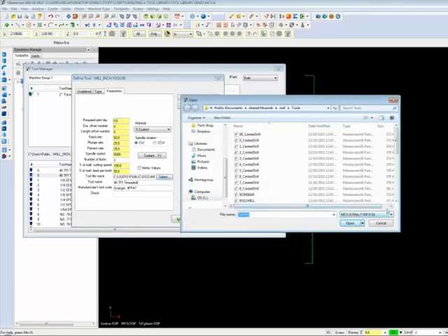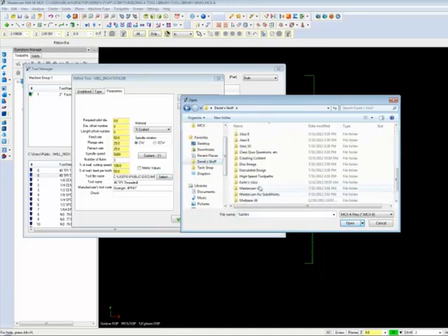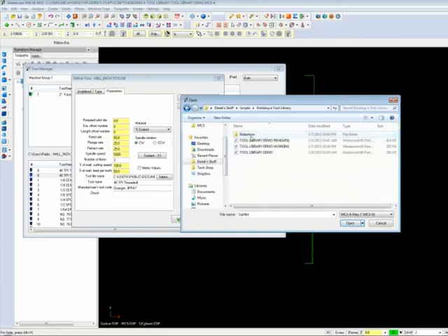No, if you actually look at what Micah just did, if you open up an existing tool and you were going to use that profile tool, all you have to do is go to the last parameter page and select the tool geometry file for the tool, wherever you're keeping that. So if you can see the screen right now, you'll see that Micah went into that tool that we just were playing with. He went in and set the select to where he had it, so that way he could go find the geometry, and it's somewhere else on his network.